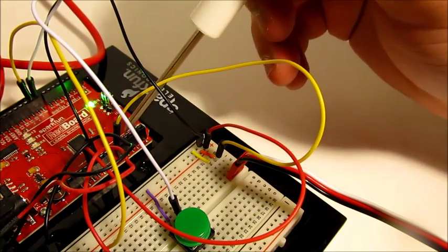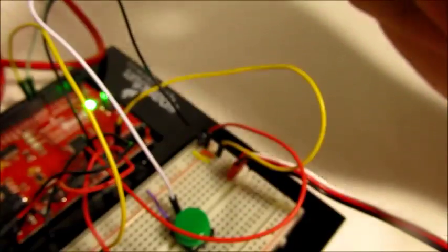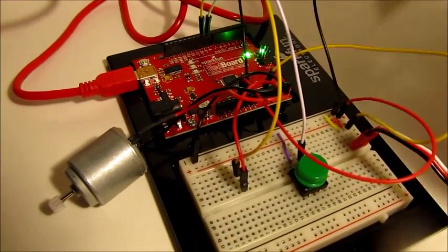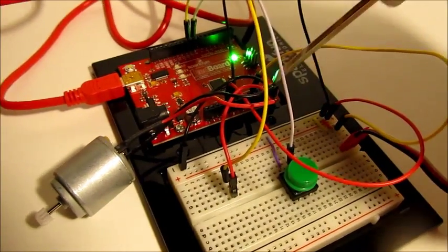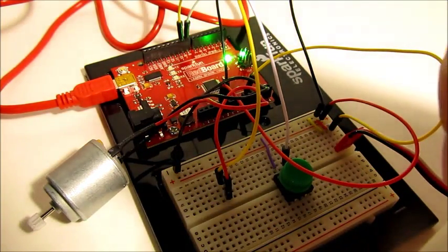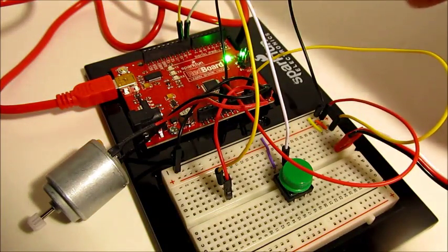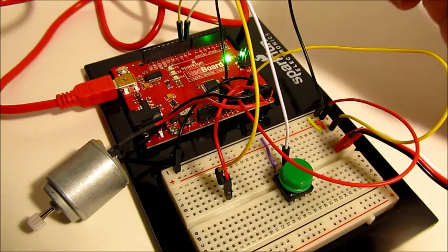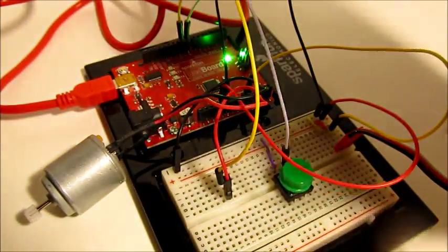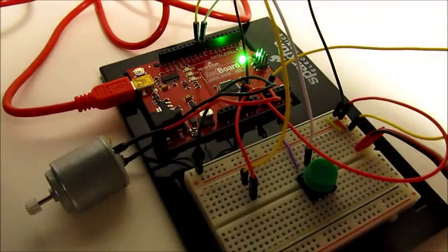When this number is above 500, at least half of the AND statement is true, and the motor has the possibility of turning on. The other half of the AND statement is that this button must be true. When the button is true and the potentiometer is above a value of 500, the motor spins at full power, because I have it set to be a digital write for the motor at high when both of these statements are true, since the speed of the motor doesn't currently matter to us.